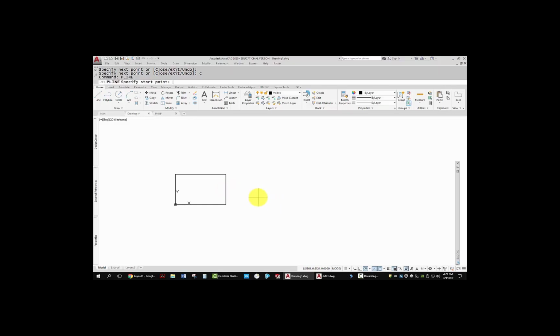If I were to use P lines, I'm going to hover over that corner, go over 2 inches so that the spacing between the two views is 2 inches. Go over 2.25, go up until it's level with the top, go to the left by 0.5, go straight down by 2. I'm going to come over until it lines up with the beginning. C for close. In this case, I have a closed P line. If I turn line weights on, because I'm on the visible layer, these lines are thick. I'm going to turn them off for right now.